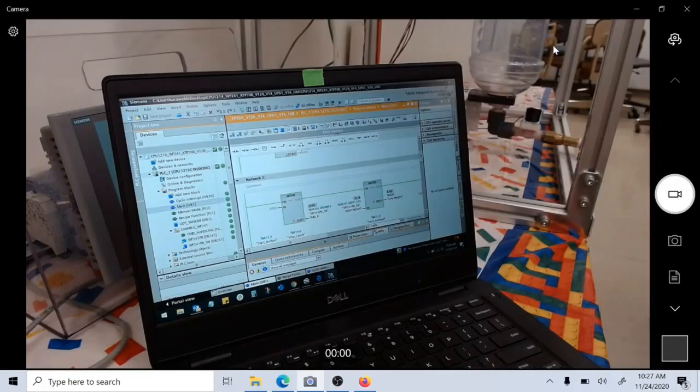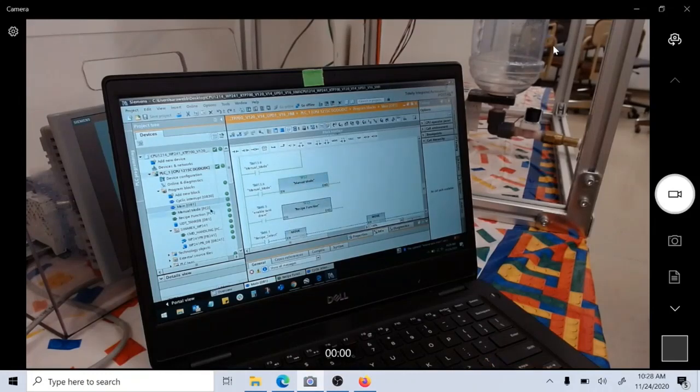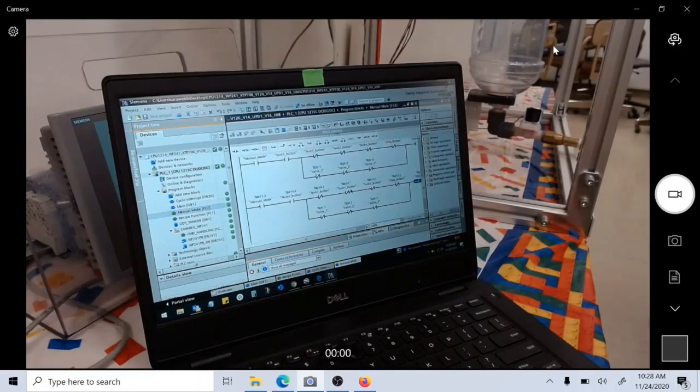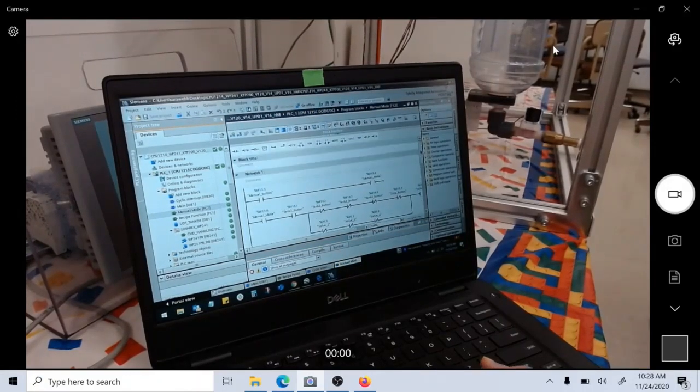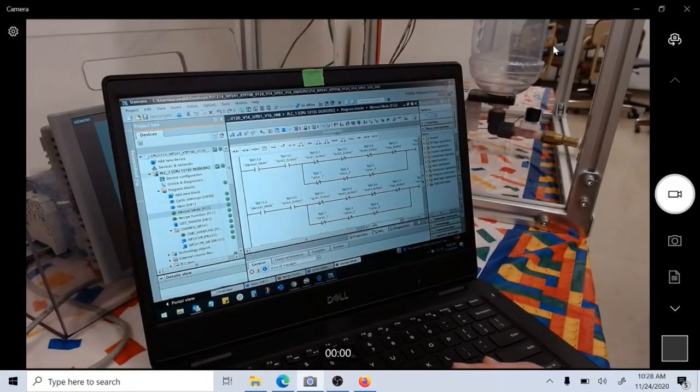So this occurs, and then this weight is converted to an int value, just to make it a little easier to work with. From there, this OB1 is really kept as a control screen. There's the stop, start in different modes, manual or auto. For manual mode, a function block was utilized to write that function, and that's really for organizational purposes, so it's not overwhelming.